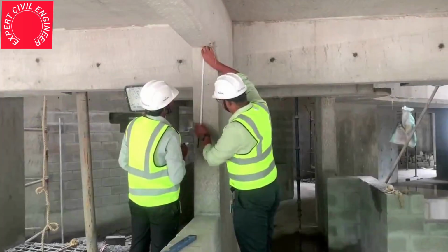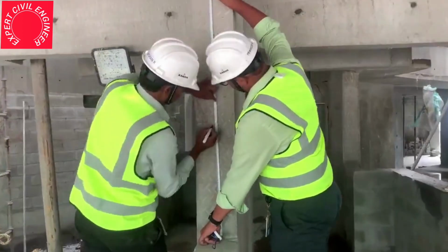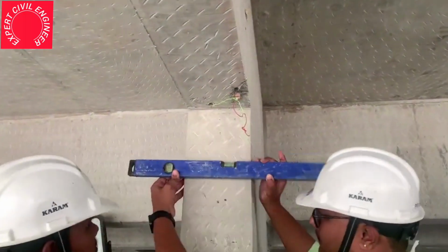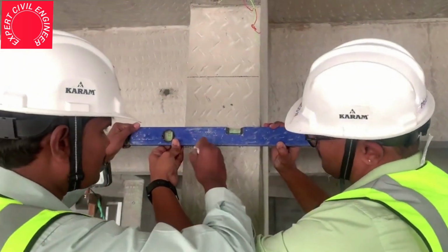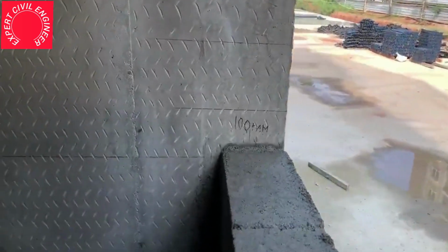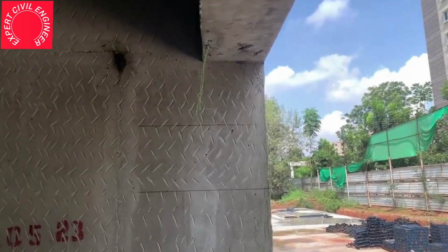After completing the blockwork up to the height of 1 meter, it is necessary to verify the balance height in order to determine the height of the adjustable courses. The marking of 215 mm, 200 mm block plus 15 mm mortar for blockwork, should be carried out on the column from top to down. This is done to ensure that the full block is constructed at the top between beam and wall.